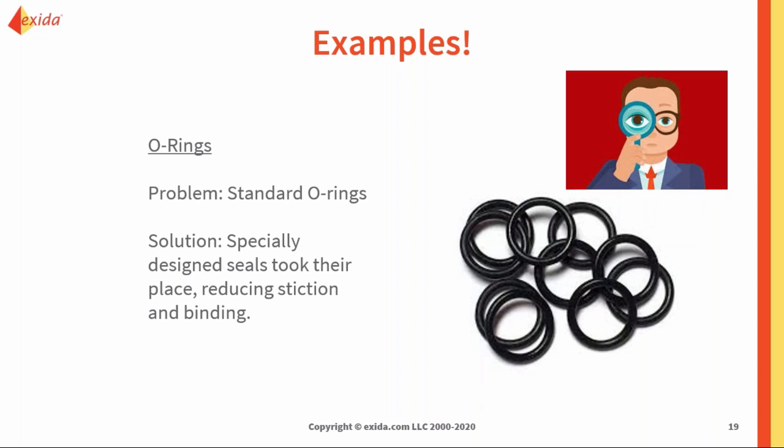O-rings. So after we looked at the study and we looked at all of the test results, we went into the FMEDAs where these O-rings were being used in certain devices, and we could lower all of the failure rates due to sticking or binding associated with the O-rings. The great part, once again, those were some of those dangerous failure rates for this device.